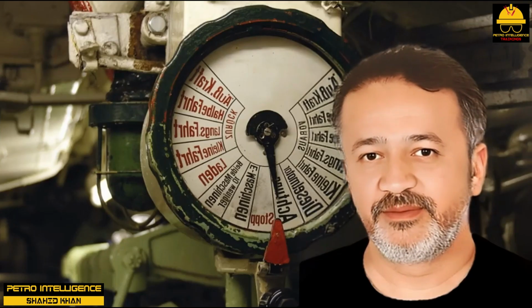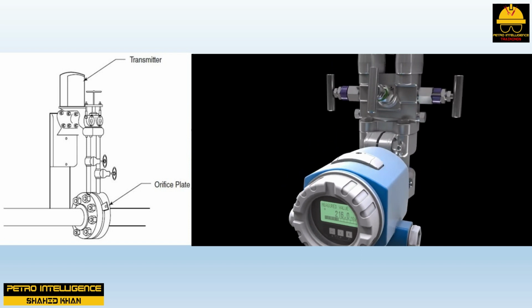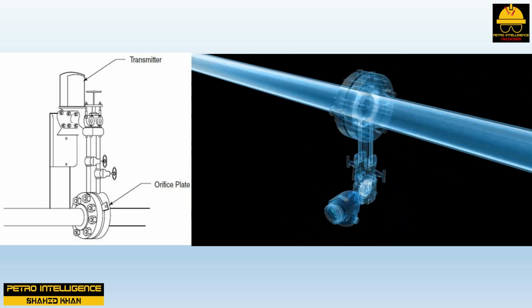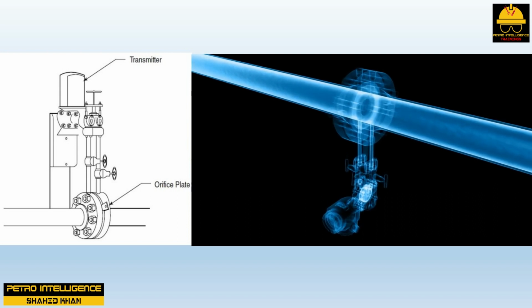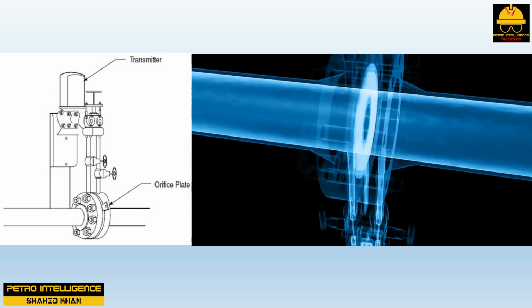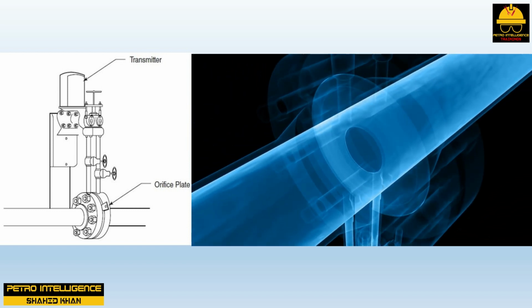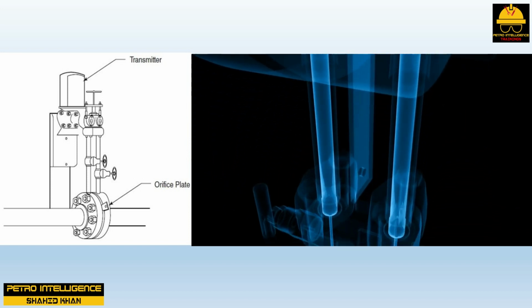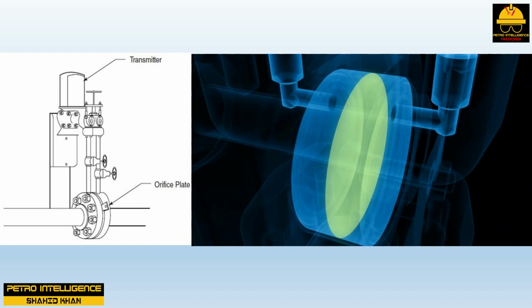Flow transmitter. Certain types of flow meters, such as orifice plate meters as shown in the picture and Venturi meters, use differential pressure to measure flow rate. Fluid flow through a pipe can be related to pressure differences inside the pipe when flow-restrictive devices, such as orifice plates, Venturi tubes, or flow nozzles, are installed. When the fluid flow encounters a restriction in a pipe, the pressure increases in front of the restriction. Fluid velocity through the restriction increases. The pressure on the other side of the restriction drops.